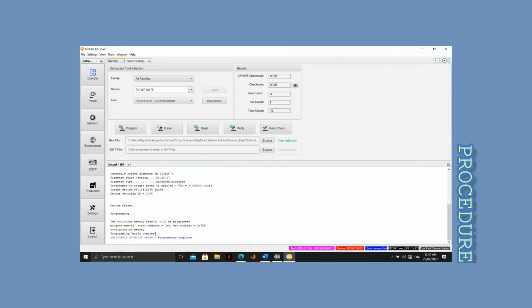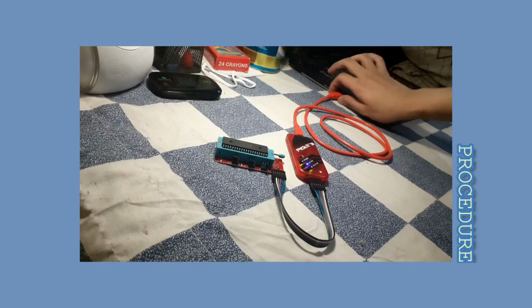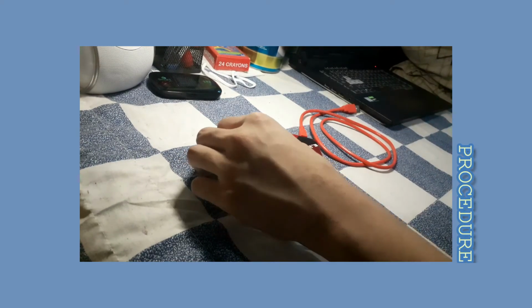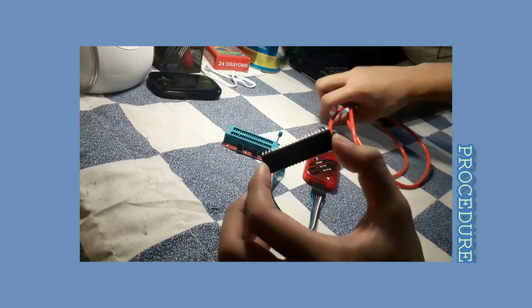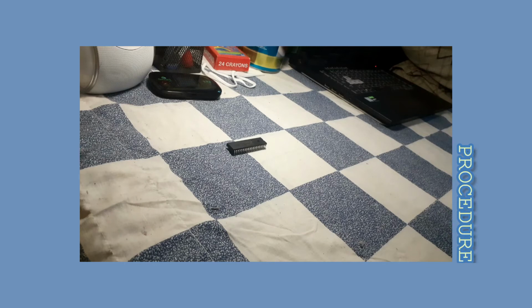Now let us try to place the integrated circuit on an actual circuit. Before disconnecting your PICkit 3 from your computer, remember to disconnect. And then you're all set to place the integrated circuit on your breadboard. Alright, now that we are finished programming, you can now disconnect your PICkit from your computer and pull the lever up. The integrated circuit came off easily from the PICkit. Now let us place the integrated circuit on our breadboard.